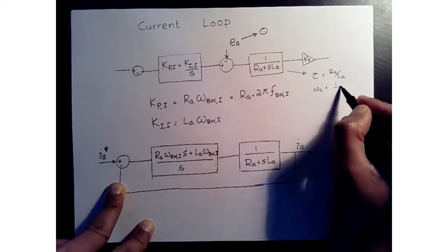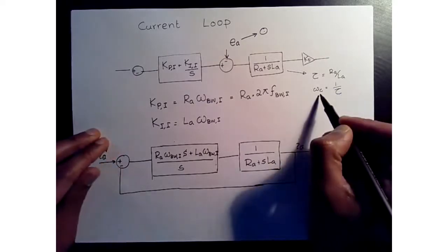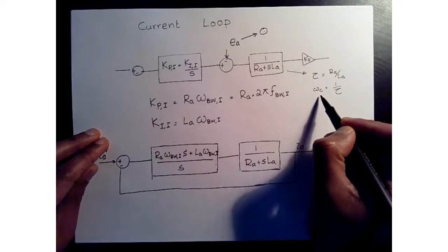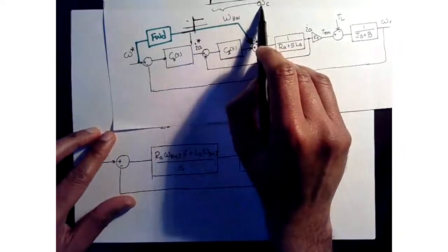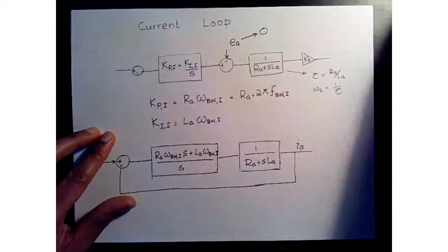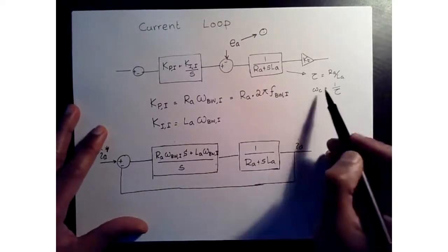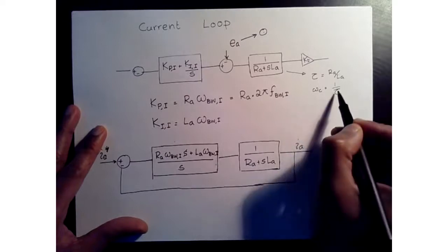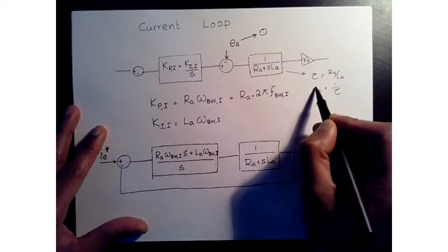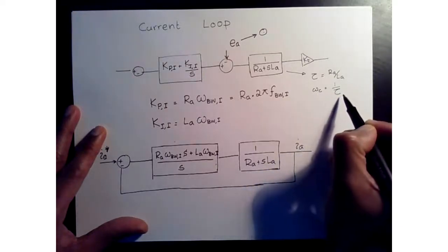Well, 1 over tau is your cutoff frequency, right? So by setting your bandwidth, you're basically choosing your cutoff frequency. Exactly, that's your pole. So by increasing the cutoff frequency, you are selecting your time constant to be faster.